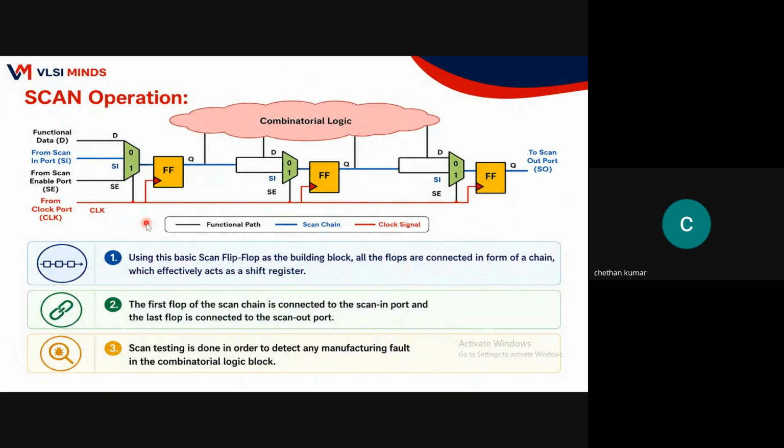We'll just convert the ordinary flip-flops into scannable flip-flops so that we'll get the controllability. We'll create our own path just to make sure that our signals are passing. Just like in a house, the walls and all those things will be constructed by the construction people, whereas along with their walls, we'll just add our logic, meaning our circuit for electricity or plumbing or whatever it is. Similar to that, we are adding it.